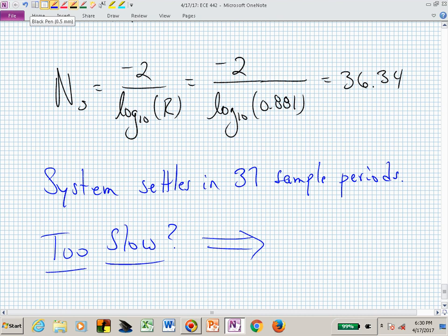You move from that point. How are those dominant poles varying relative to their magnitude? They're going away from the origin, aren't they? So now your radius is getting bigger. You're getting slower. You might get faster in terms of peak time, but in terms of settling time, you're not really getting any faster than that. So we're going to have to change dramatically the structure of this pole zero pattern for the closed loop poles.